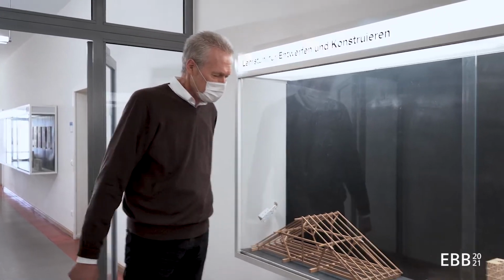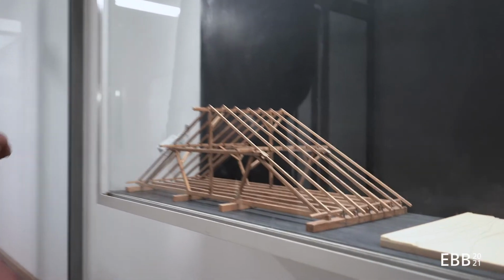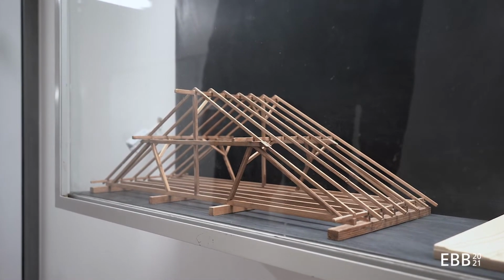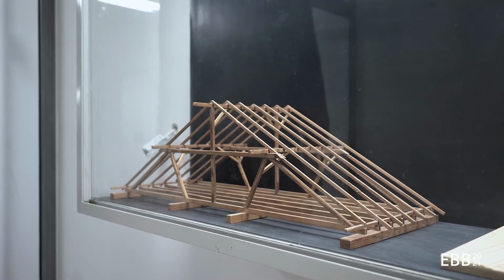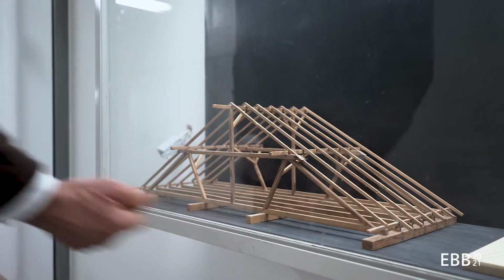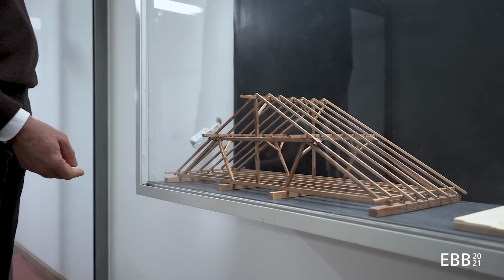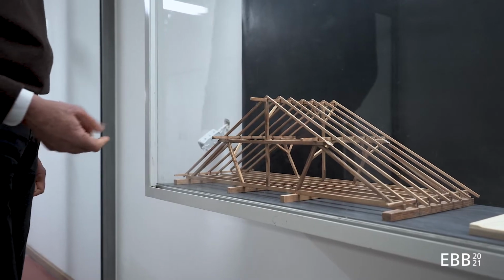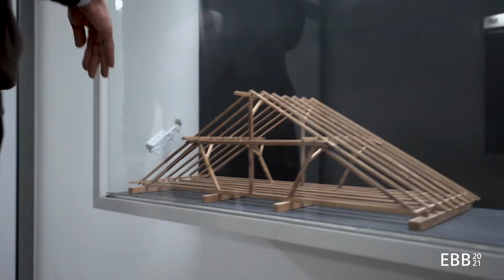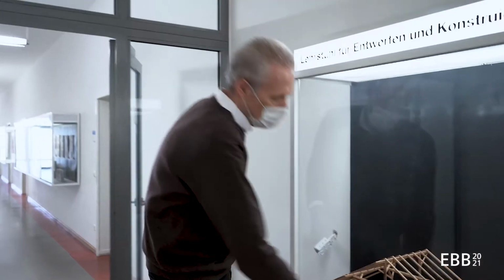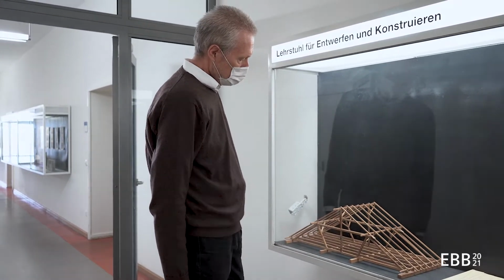So here, in the example of a purlin roof, you can see that the horizontal structure of the roof rests on what I would interpret as walls, and you have a floor slab that consists of wooden beams, and then the roof structure is integrated in these wooden beams. What they have been trying here is to integrate the bracing in both directions, as well in this connection between the beam and the rafter structure.